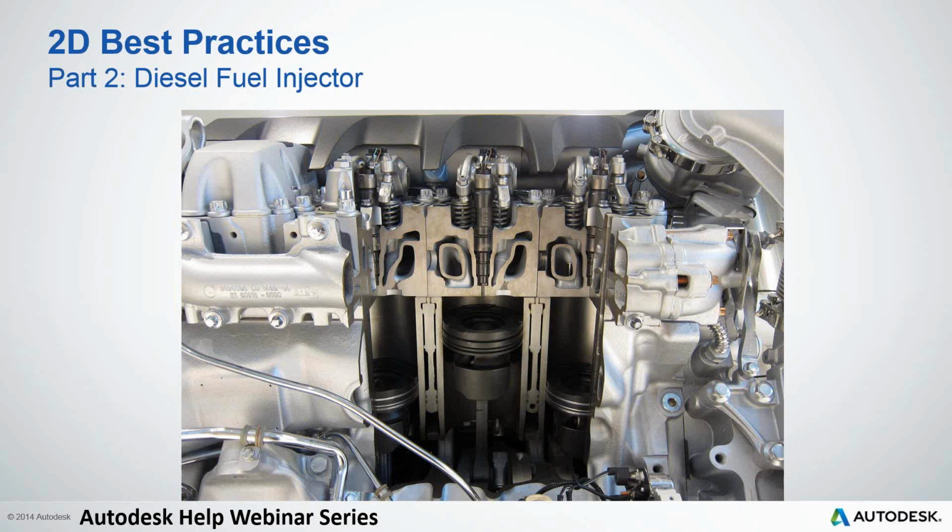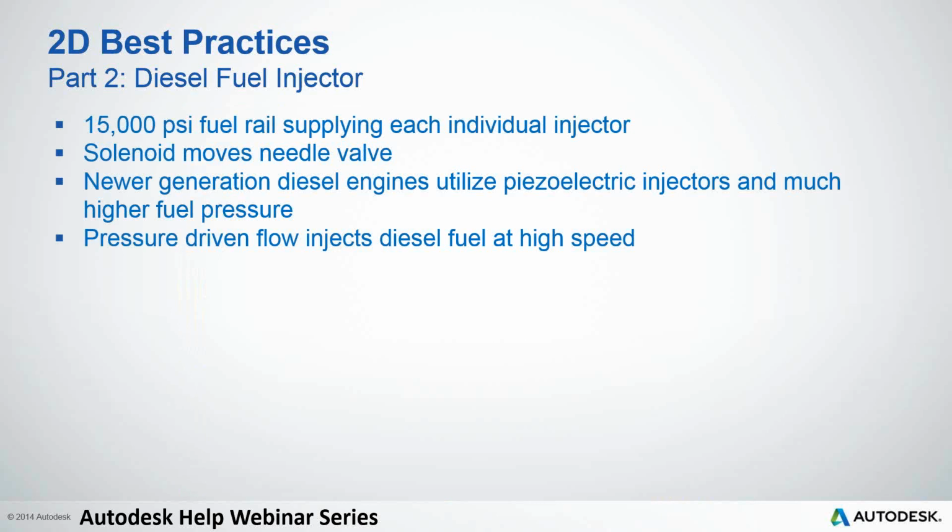Now these fuel injectors usually are supplied diesel fuel at over 15,000 psi. The newer ones are much higher than that, but even in the 1920s or 30s, they were up at 15,000 psi. And depending on the engine, compression ratio would be a few hundred psi. So they have to get that fuel injected as fast as possible. Sort of direct injection here.